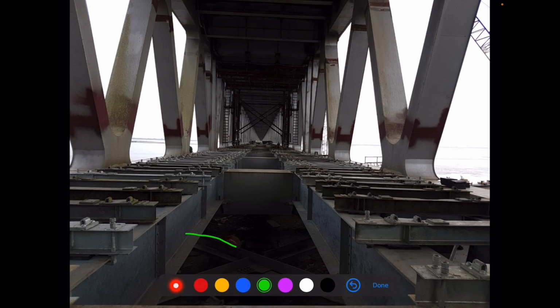So these are stringers. A stringer here looks like a built up I section with stiffeners provided at a few locations. Over these stringers, these I section steel bridge sleepers have been provided. Basically it is an I section, but if we keep it like this, then it becomes an H.